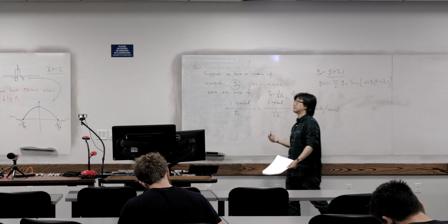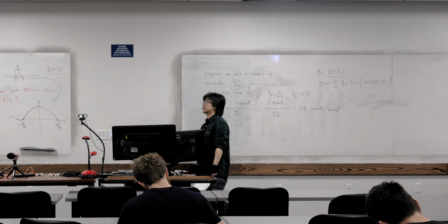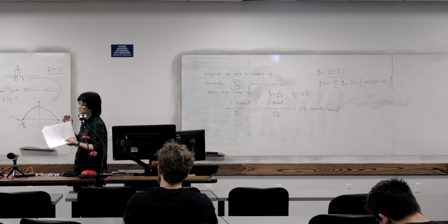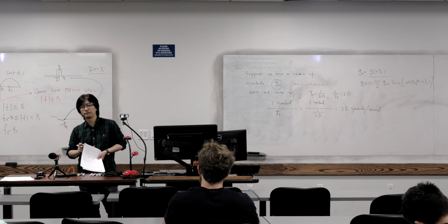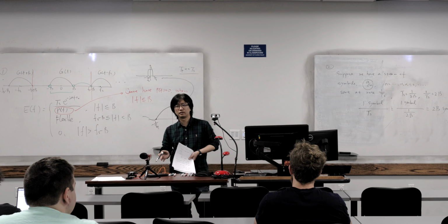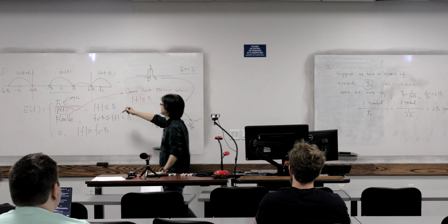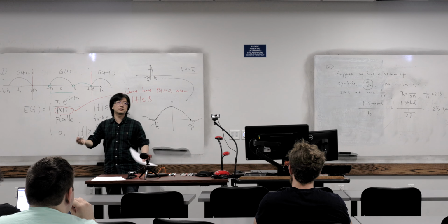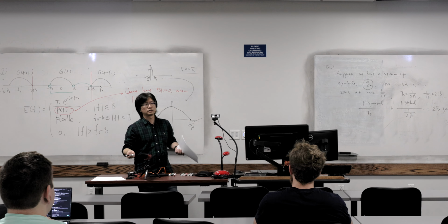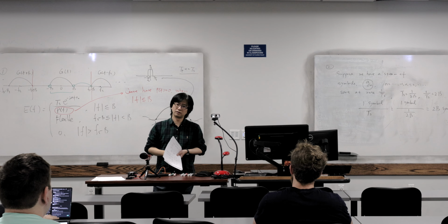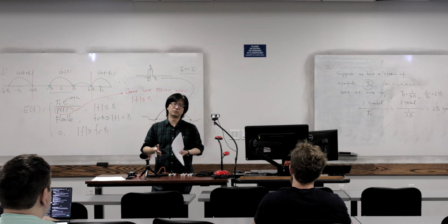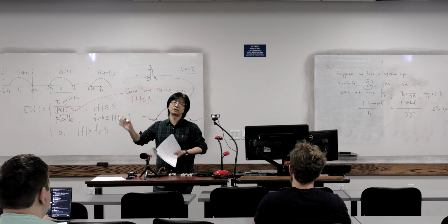So what does that mean? I'll repeat it: for 1 second, we transmit 2B symbols. And what is B? B is the bandwidth of the signal. It means that if the signal has more bandwidth, we can transmit more symbols, and more symbols probably mean more information. This is our current understanding.